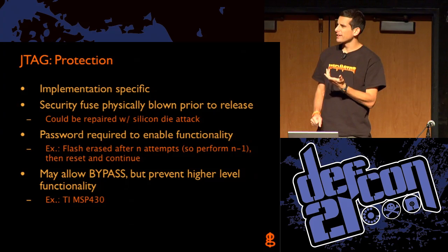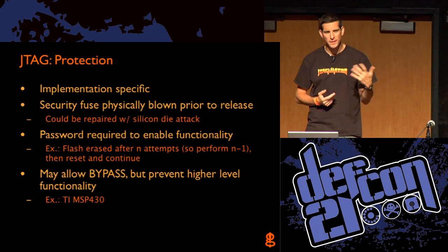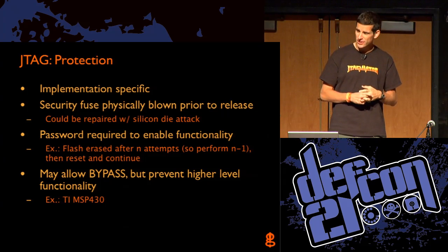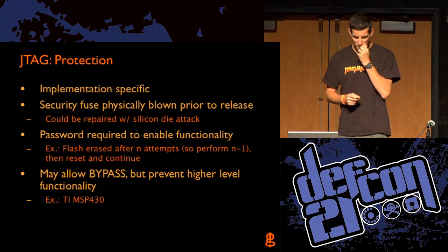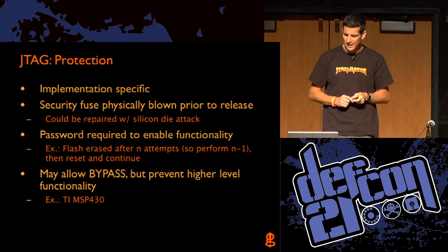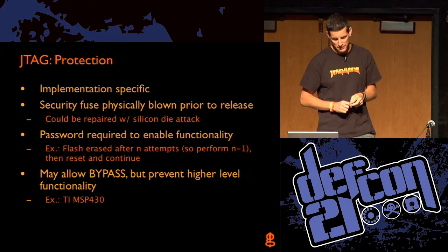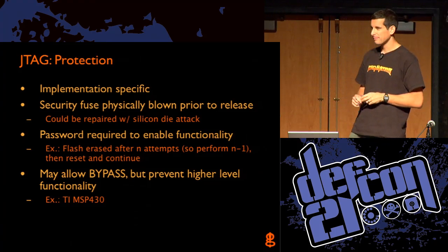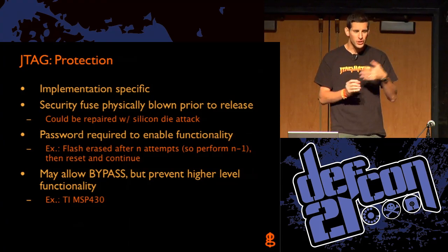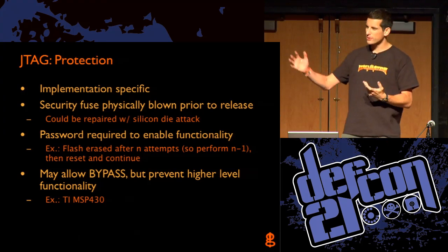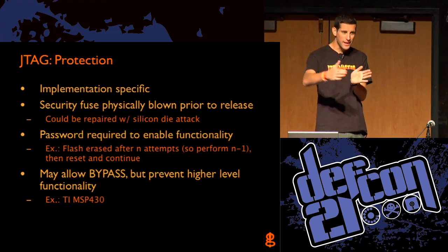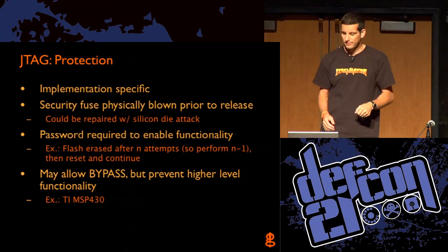If you do this enough, you will run into JTAG implementations that do have some sort of protection. But like anything else, most people don't use protection, right? That's pretty safe to say, especially at Defcon. But you do run into it once in a while. Vendors are aware of what's going on. But making changes in silicon is really hard, right? So even if a vendor knows about JTAG and tries to do some sort of password protection, it's a big change for them to do that. Then they're going to have to update everything else from that point that uses JTAG.